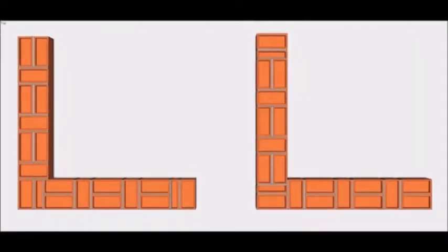Now, in course 2 of one brick thick wall in double Flemish bond, we will start just opposite from course 1. Instead of starting from header and a queen closer, we will place a stretcher and a queen closer to start the wall.